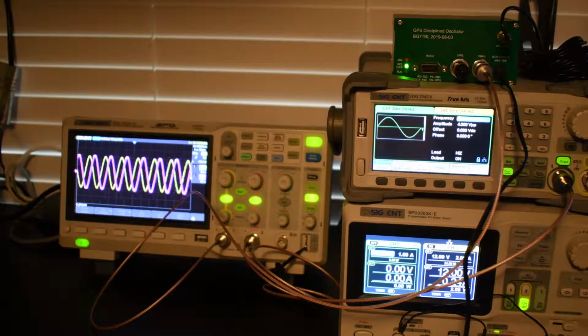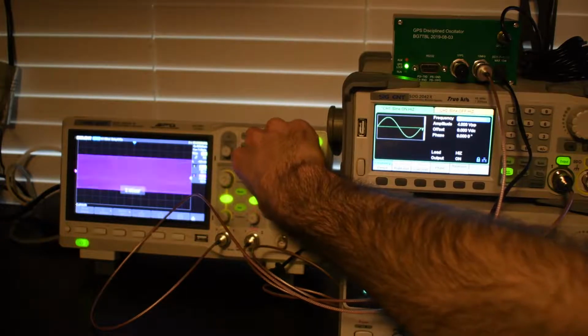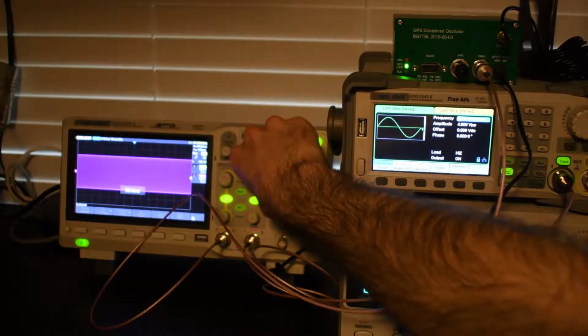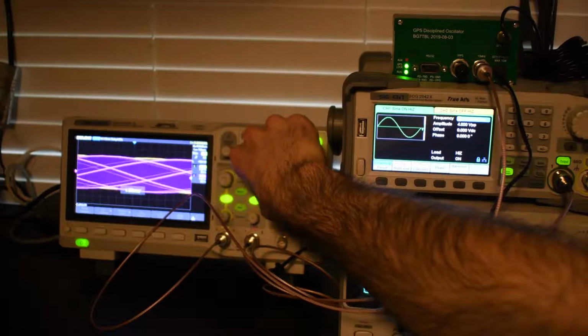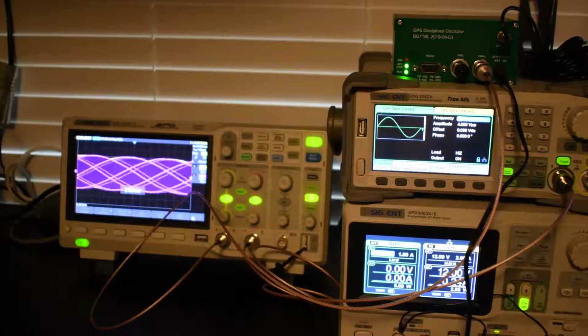So if we want to measure these two more precisely than that, the first way you might think about doing that is zooming way out and acquiring both of these together. So you'd want to get kind of close to the minimum Nyquist rate. So you'd get close to where you're sampling at least twice per cycle, but not many more times than twice per cycle. And so that might be the first way you'd compare the frequencies. Just sample the two, do a Fourier transform, and see where the peak is.